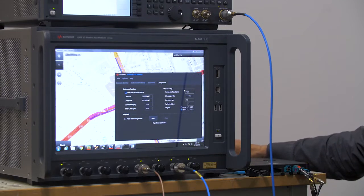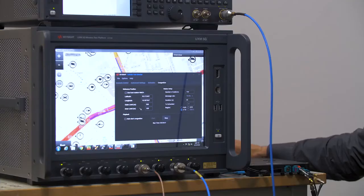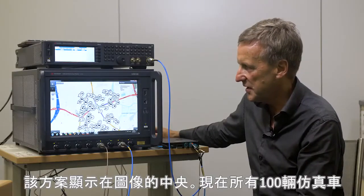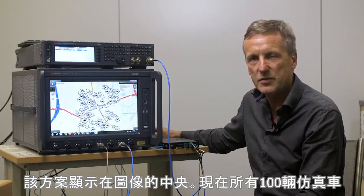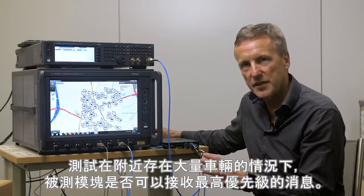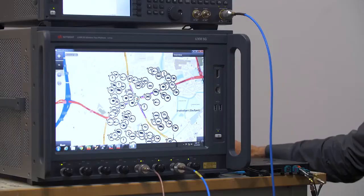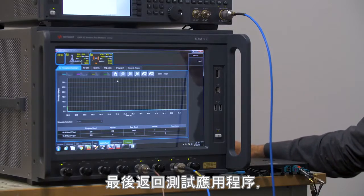We're going to create 100 simulated vehicles in the area of the scenario. So I'm going to start. If I go back to my WaveB Touch and expand out, we can see the scenario in the center of our image, but we have 100 simulated vehicles all transmitting over the PC5 link. So the test would be, does my module under test still receive the highest priority messages in the presence of all these other vehicles?